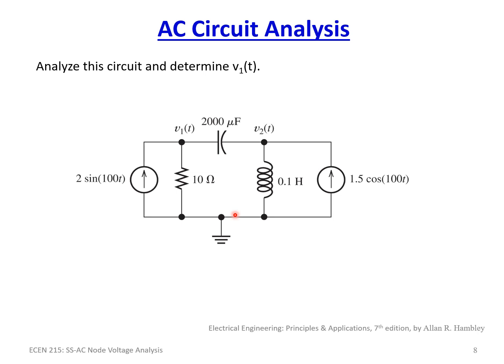Again, the reference node can be any position as long as it is the node that all of the analysis is done by. You cannot have multiple reference nodes. So this is node 0 as it's known, or the reference node. So we have that as our basis point. And then of course the next step in nodal analysis is to assign the nodes, which was already done for us here. We've called this node 1 and this is node 2. So that is the problem that we have.